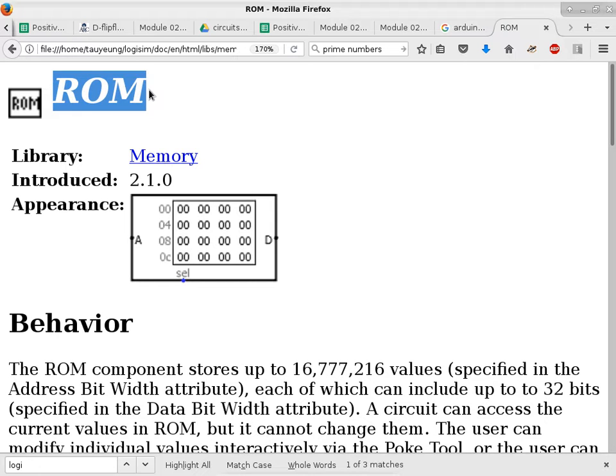I don't know how much margin they leave, but it's actually more than that. The reason they need to do that is because they know sectors will burn out. So what they do is they remap sectors. The physical sector here may actually be something else when you address it from the serial bus. The controller on the SSD itself is managing all of these things to give you the best longevity out of the device.